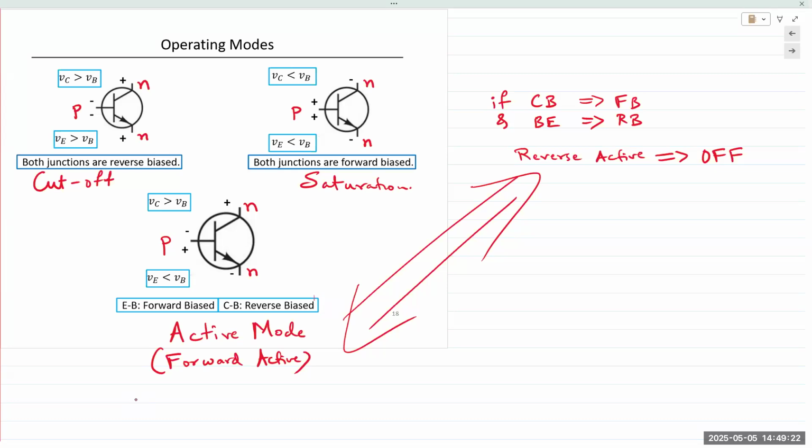That's absolutely correct. So remember, the transistor, the BJT, is not a symmetrical device. The emitter is the most heavily doped, so that's where the majority of the charge carriers are originating. If it's an NPN transistor, the emitter is supplying electrons. If it's a PNP transistor, it is supplying holes. If the base emitter junction is not forward bias, there are no charge carriers present.